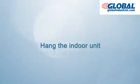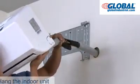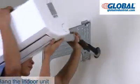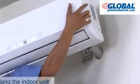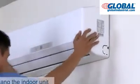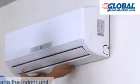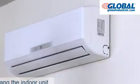Hang the indoor unit. The copper pipe and connecting wire after wrapping are threaded slowly through the wall hole to prevent colliding with the wall or bending. Hang the indoor unit on the hook of the mounting plate. Insert the lower part of the indoor unit into the groove of the mounting plate.